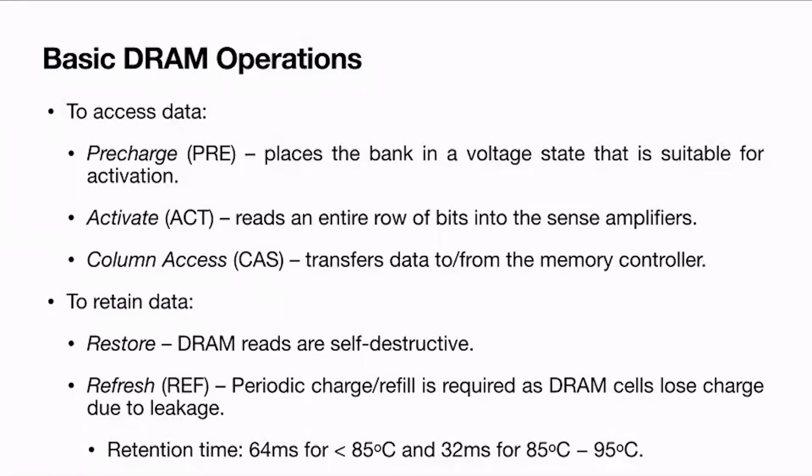Every read you perform in the DRAM array, you have to restore it back, irrespective of whether you have done a refresh or whatever. A refresh is also exactly the same as a restore, because a refresh is nothing but reading the data into the sense amplifier and writing it back into the DRAM array. So all these operations you have to do every time, and this again adds extra latency to the overall DRAM operations and so on.